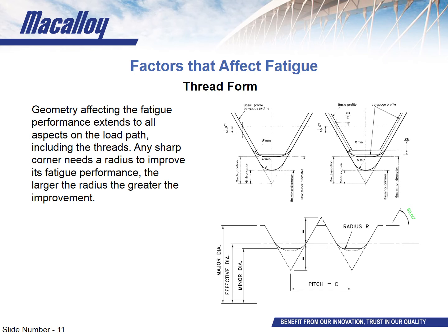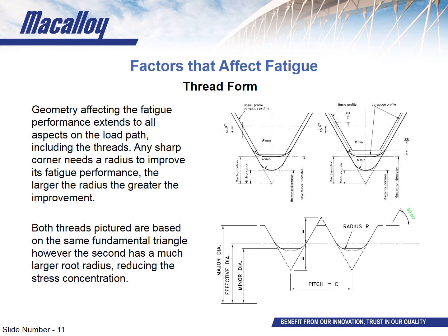Now, while the stress evens out in areas away from the transition, the stress is compounded at that corner, forming a stress raiser, otherwise known as a stress concentration area. Just as with bending moments, a concentration of stress at one point correlates to a larger stress range as that load fluctuates. Now this in turn reduces the fatigue life as stress raisers are hotspots for crack initiation. The most commonly present example of this in bars and civil engineering is actually the thread form itself.